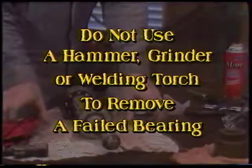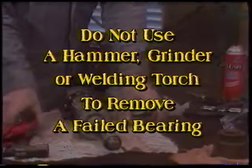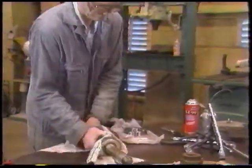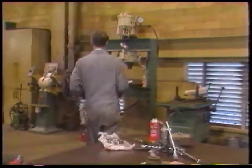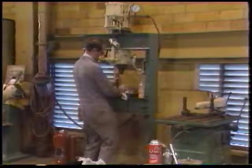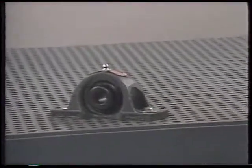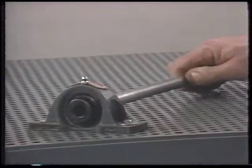You may be tempted to break it off with a hammer, grind it off, or even use a welding torch to cut it off. These methods are dangerous and will usually damage the shaft or bore. The best practice when removing a failed bearing is to use a puller or a press adapter. The fit between the bearing ring and the shafts and bores is critical.